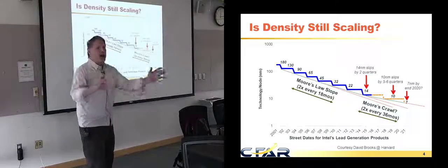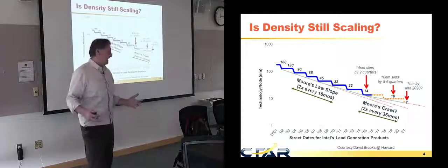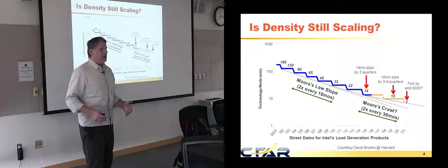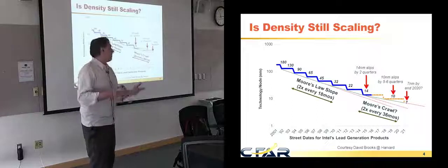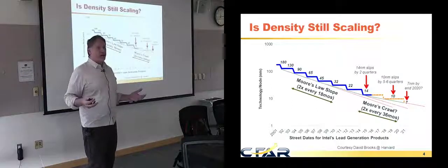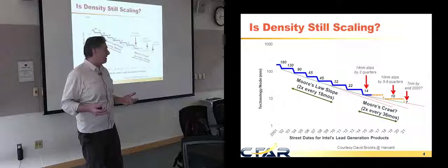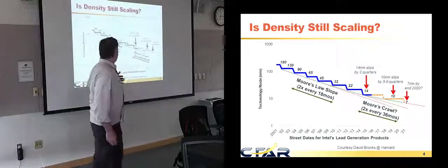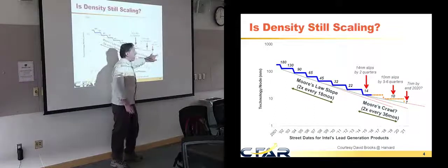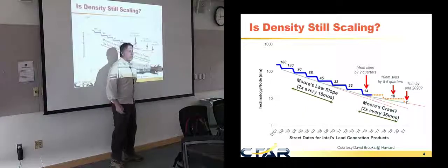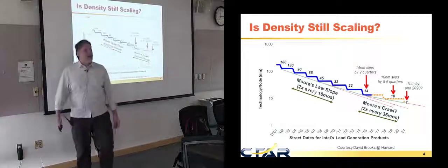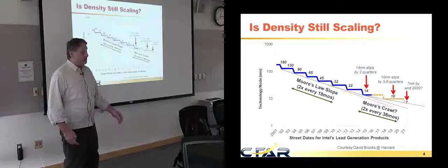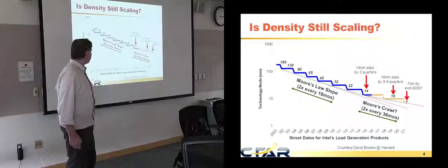Now, will we switch over to non-silicon? Unlikely. The investment in silicon is too great. Will there be non-silicon devices integrated? Perhaps. But again, those aren't going to provide the scalability that silicon has over the last 40 years. Those are still made out of atoms. And we're really at the atomic density here. At 7 nanometers, you're talking only 14 atoms in the width of a minimum size transistor. It's just not a lot further down you can go from there.